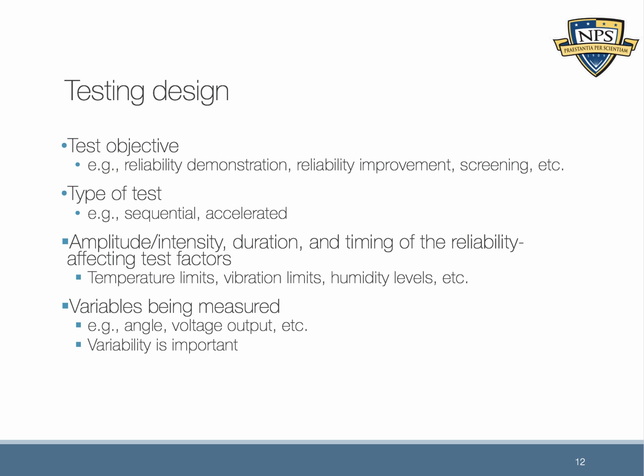So you have to ask yourself before you start the test, do I need more granularity than that? Do I need to know every 10 degrees Celsius that the unit's working? Potentially you do. And it's interesting because that'll actually affect your test. It'll affect your ramp rate, how quickly you can warm up the temperature chamber, because it'll take time to turn on the units and test each one individually. If it's done automatically, which it most likely will be, you can probably do it fairly quickly, but it may take 5 minutes, and so your ramp rate of your temperature will be limited by that ability. So also important to kind of understand.